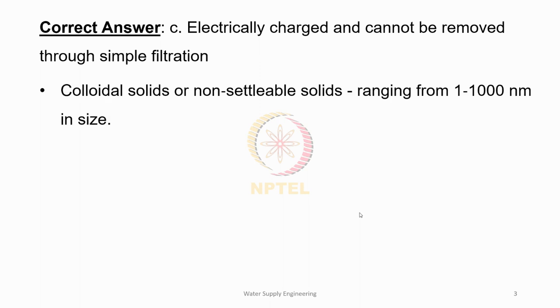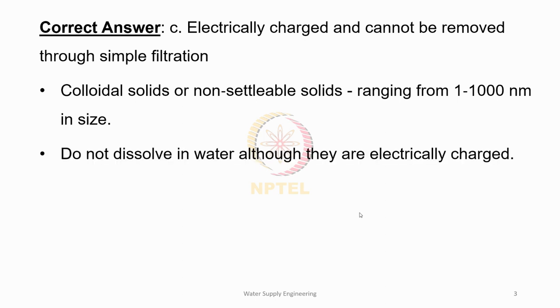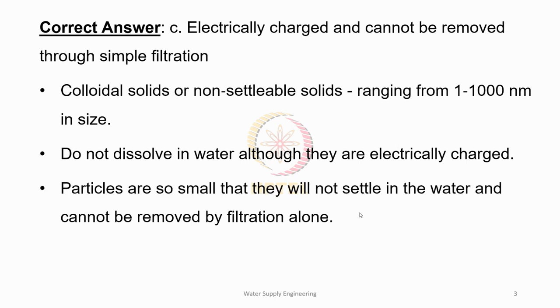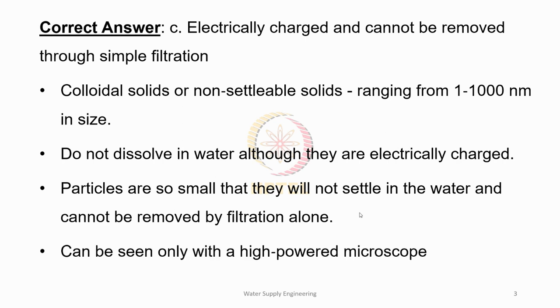The colloidal particles, or non-settleable solids as they are called since they do not settle under gravity, typically range between 1 nanometer to 1000 nanometer in size, and they are invisible to the naked eye. We need to use a high powered microscope to view them. Though they are electrically charged, they do not dissolve in water. Since the size is small, they do not settle under gravity. Also, they are not removable by filtration.